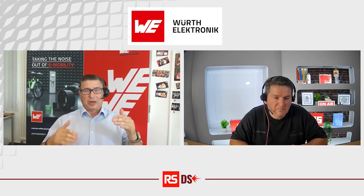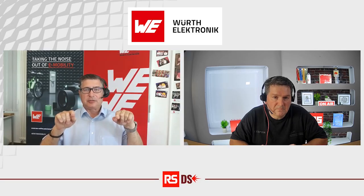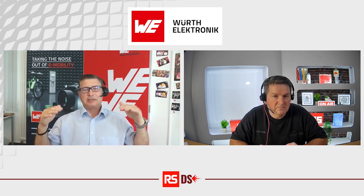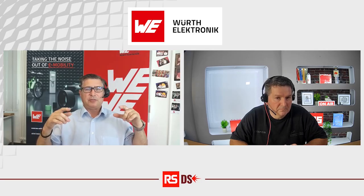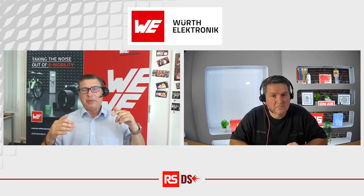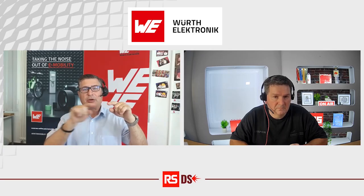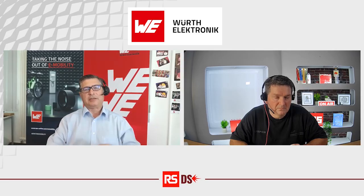Sometimes if you're not 100% sure, instead of using LC, I put a second C, so I have my pi filter because it's CLC, and then I say, okay, with the LC I have some result, but the pi filter is much more effective. If I see that with the pi filter I still do not improve on my LC, it means maybe my system impedance is lower, so I go back to the LC and I add another L, so I have actually a T filter, and the T filter, acting in a lower system impedance, is much more effective than a pi filter or LC filter. And this is how I play with the filter normally.